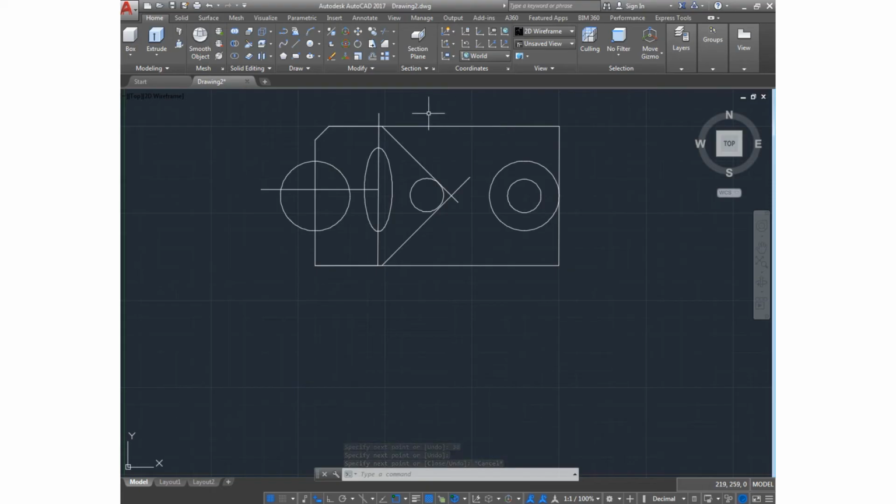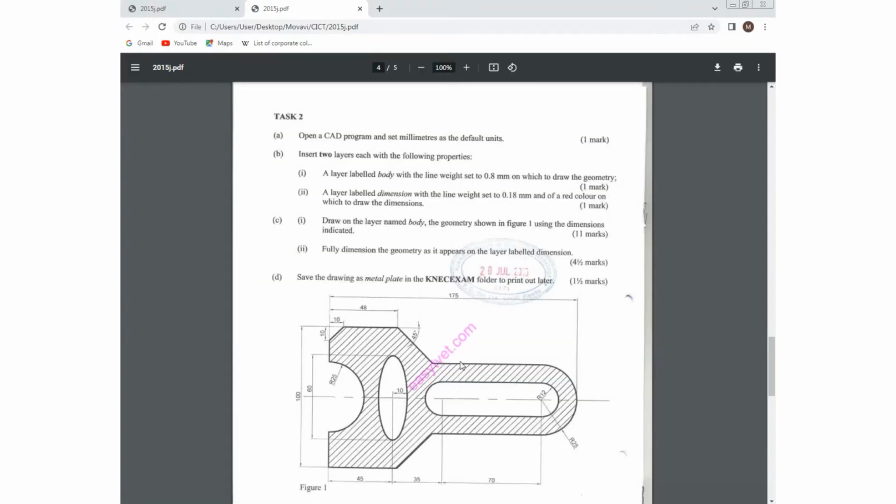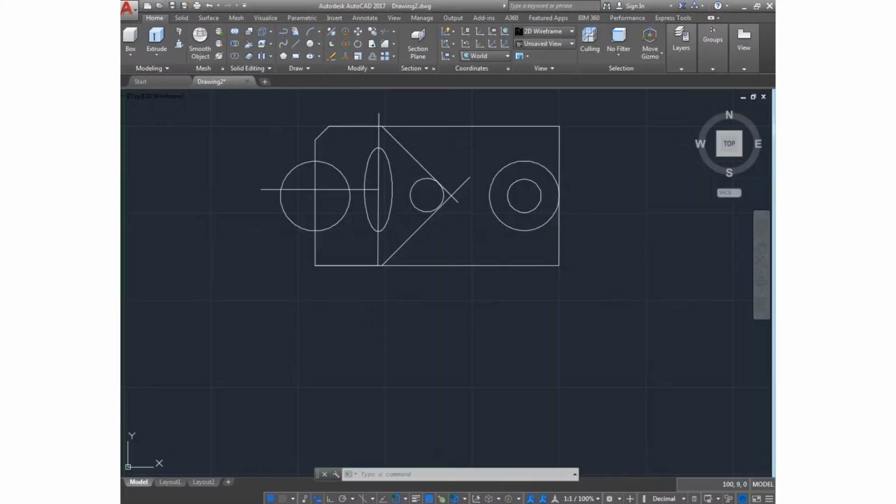So our drawing is almost over. We only have to draw 2 more lines. The lines I'm drawing right now are the one from the end of the circle to where the 45 degrees angle line is. So I'll select the line. Seems I cannot draw on top of the circle because the line will go back to the center. So I'll start on the center and go a distance of 25.